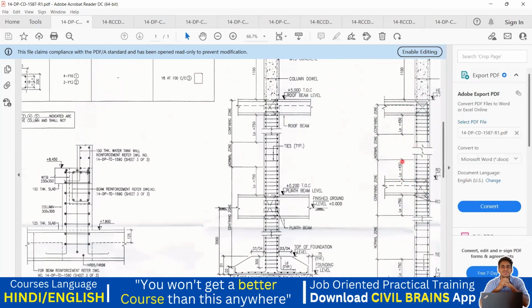So till what height you are supposed to provide, they are going to give the length L0 equal to 450 mm. That is from the top of your slab up to 450 mm, you are supposed to give your lateral ties at the closer spacing. Similarly, from the bottom of your beam, from the bottom of the beam to this length, it has to be 450 mm. And here you have to give at the closer spacing. Remaining you can give the normal zone.